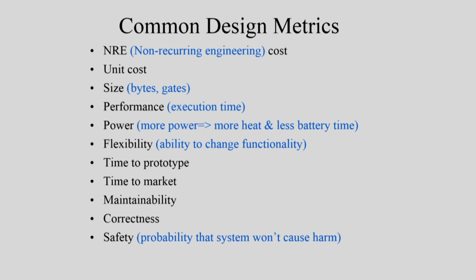So what we try to do is that we sensitize the participant to common design metrics with which we understand embedded systems. Things like non-recurring engineering cost, meaning the cost which you incur right at the beginning in order to design the artifact or to conceptualize it, and after that is the notion of each piece cost, which is the cost of the material and actually producing the device. That leads to a unit cost, where chips have a very high NRE cost, almost millions of dollars, while the unit cost is very low.